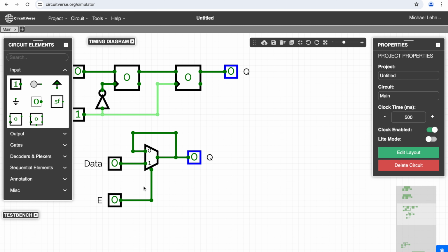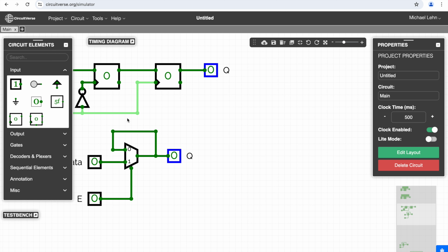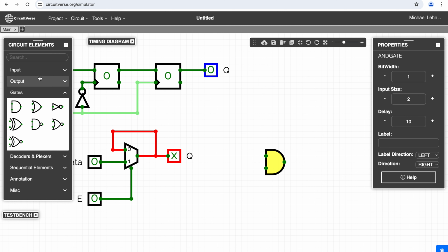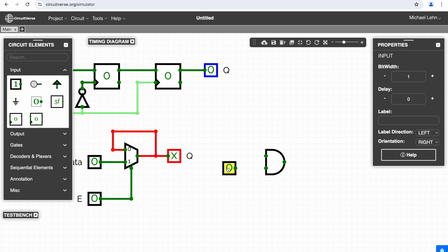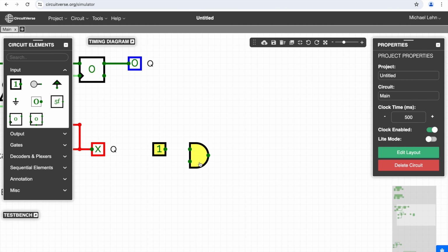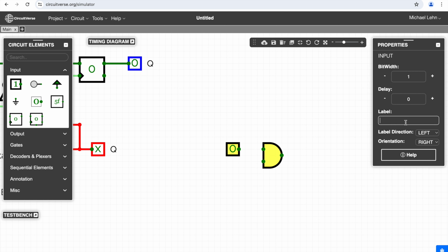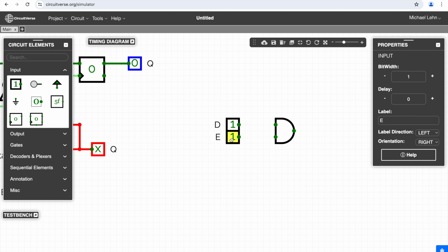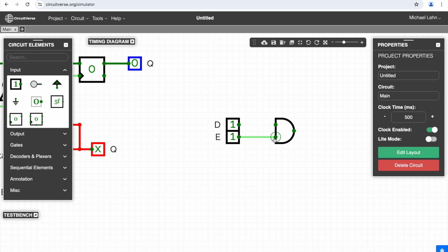So this also could be expressed, by the way, with logic gates, with AND and OR gates. Basically the Boolean expression that I showed you before. Let's move this a bit. Let's say this here is enable E. Let's say this here is Q. This is D. Then if enable is 1 and D is 1, this should be the value. This is the first part of the equation.